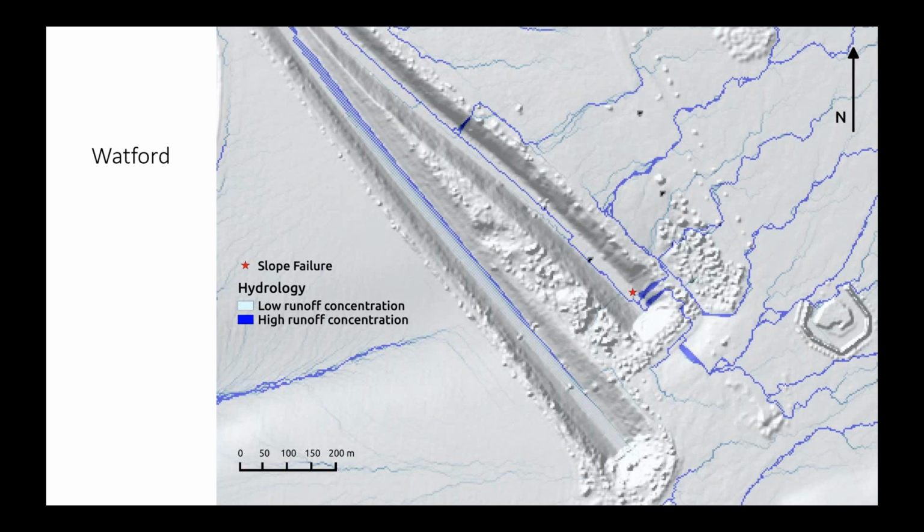So what we do is we take topographic data, and we then run some numerical models of hydrology and flow routing. So there are flow routing algorithms, and then that flow is propagated into a stability model, which balances the frictional forces against the downslope forces, and we try to come up with places that seem to be at risk. So this is a map of the hydrology that was derived from a 1-meter topographic map of the Watford site. And in a second, I'll show you our best estimate of the landslide risk at this place, or at least the hazard at that area.